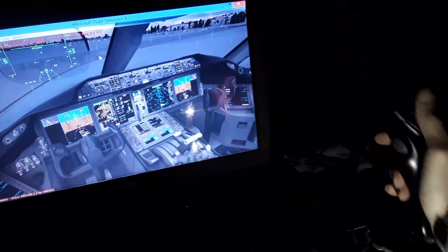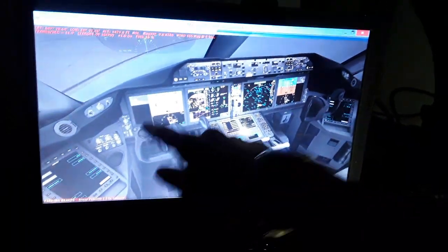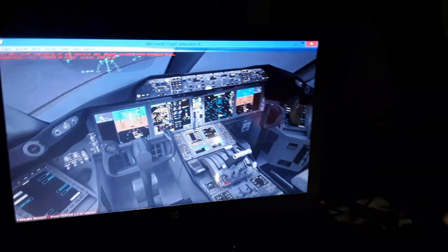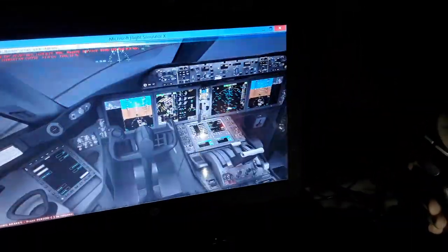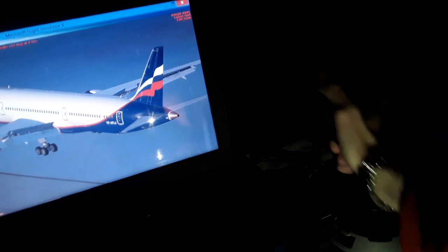So you're gonna see I'm gonna use all these flight controls here. Use the side stick for climb and descent. You can see make turns left and right. We have the horizontal trim stabilizer over here. I will talk to you about the switch, the autopilot disconnect, the head up display declutter. So you're gonna see a few more things. For climb and descent, you use the elevator like this.